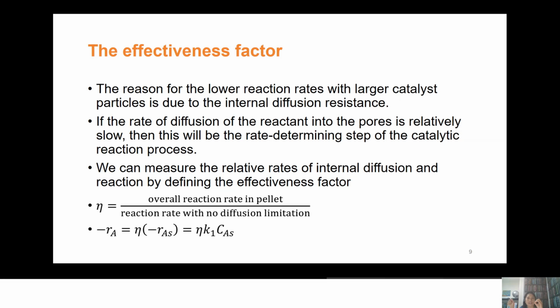So the concentration of reactants inside the pore will get depleted, and you will observe some slowing down of your reaction. The reactant concentration in the pores drops rapidly as it's consumed faster than it can diffuse inside the pellets. So if you average the rate of reaction over the whole pellet, you'll find that it's less than the rate at the surface.